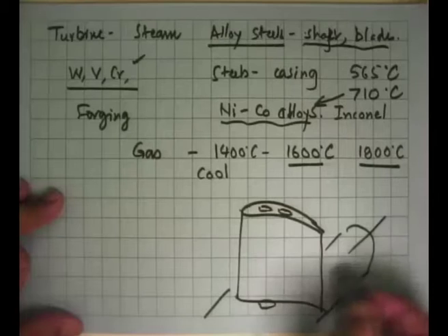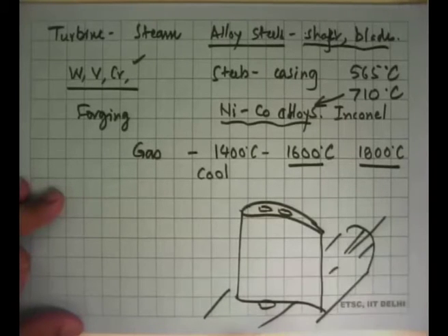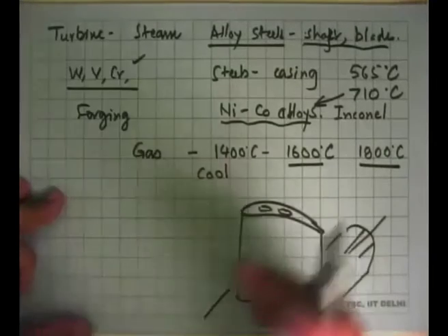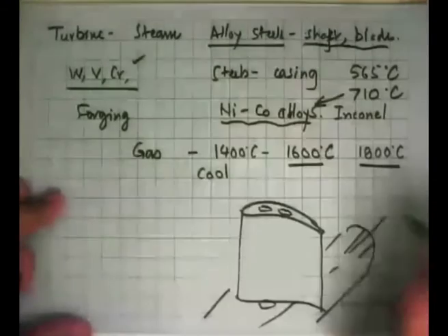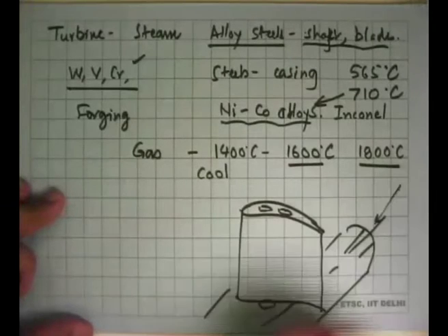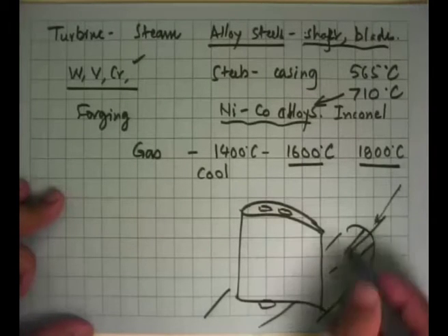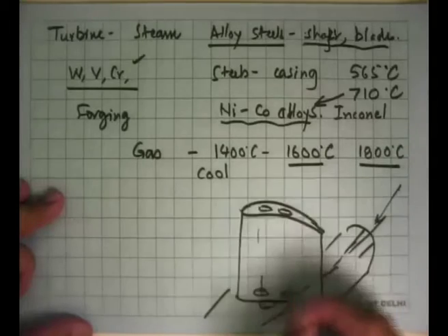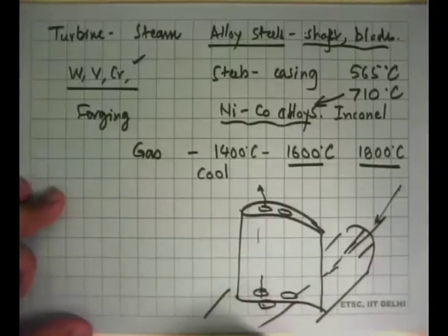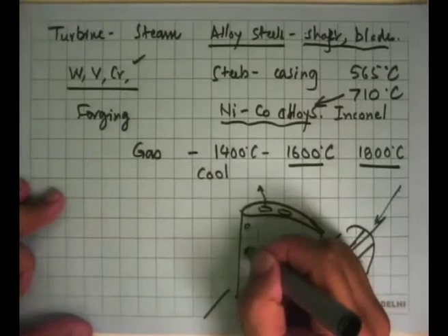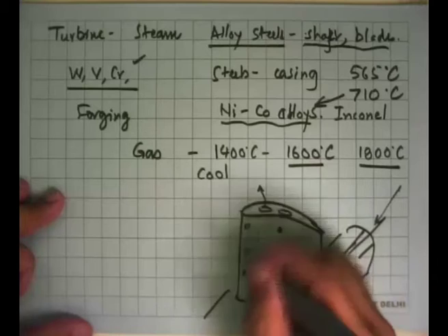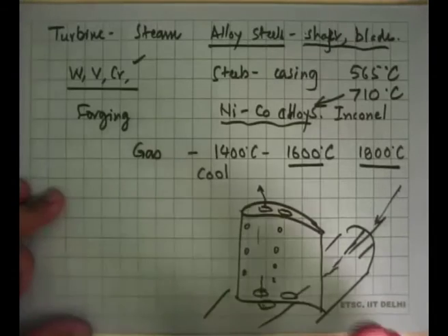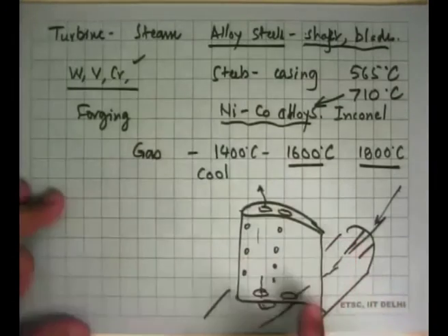So this is the shaft. This shaft is also hollow, and some of the air from the compressor, say about 700 Kelvin, 800 Kelvin, 900 Kelvin temperature, instead of going to the combustor, bypasses that, is pumped through the passage in the shaft, comes in, connects with openings inside the blade, moves through hollow passages inside the blades, comes out either from the top, or there are small holes on the surface of the blade from which this air comes out, and what it does is that this air goes over this, and right next to the surface forms a small blanket of cool air.